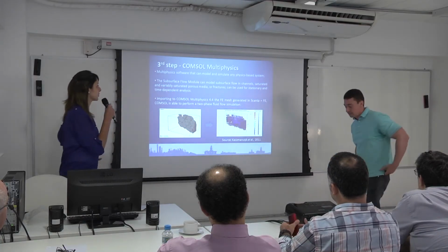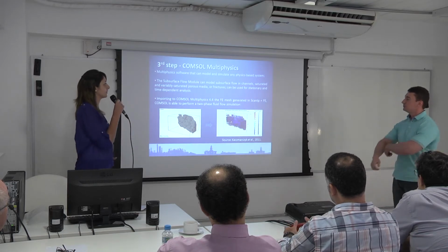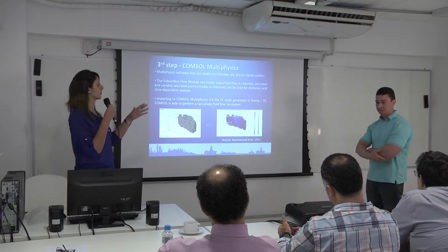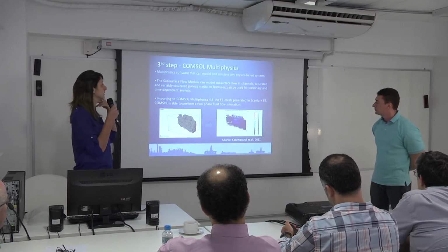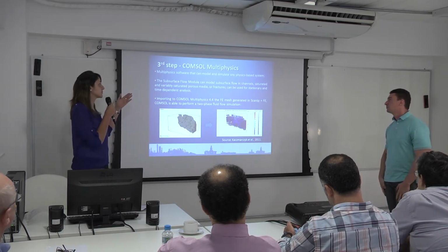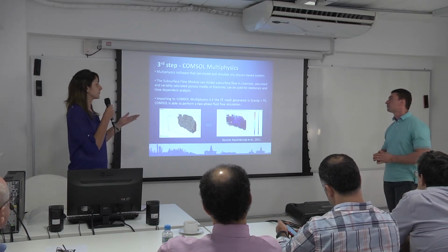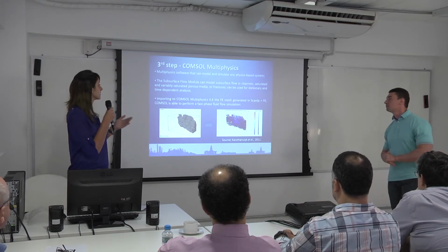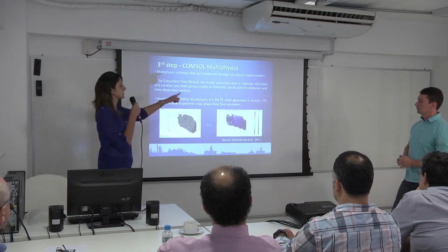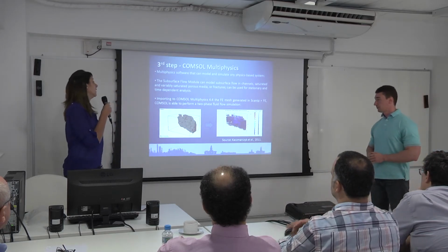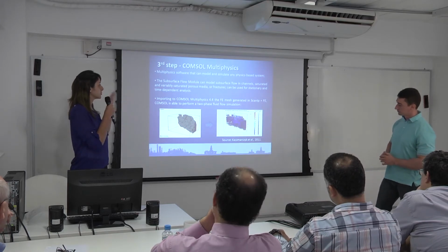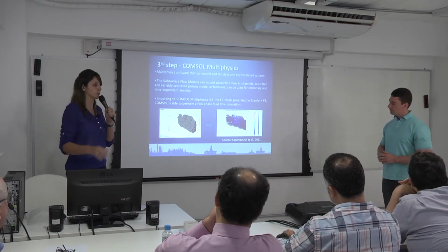Now talking about Comsol Multiphysics, it's a software that can model and simulate any physics-based system. So you can use it to perform simulation in electricity, magnetism, chemical, whatever. We are going to use the subsurface flow module that can model subsurface flow in channels, and saturated and variably saturated porous media. In our case, we are going to use a stationary model. And then we are going to import the image from Simpleware to Comsol to perform a two-phase fluid flow simulation.